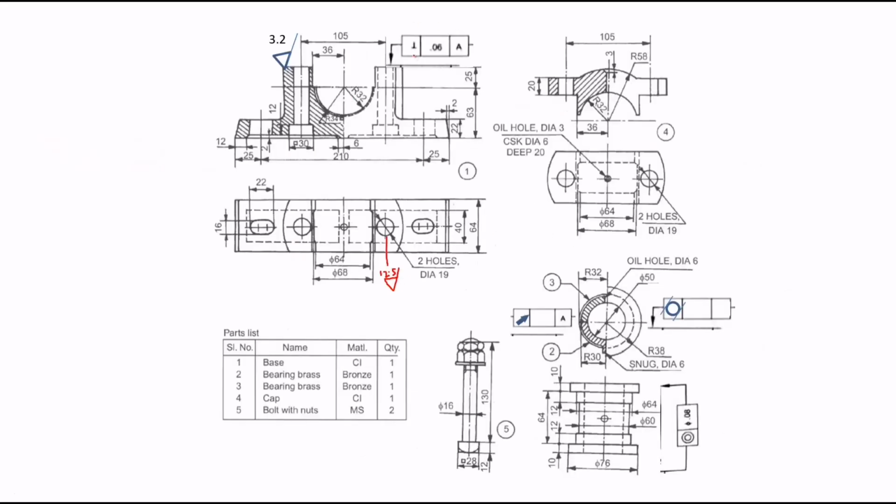Look at this. Here this is a perpendicularity symbol, this is the cylindricity symbol, this is a concentric circles or concentricity symbol, this is the run out symbol. So how are these symbols used here? This symbol is nothing but perpendicularity, meaning the two lines of the surface are making 90 degrees. This run out is for a circular object which maintains its axis, so we can say it as run out.